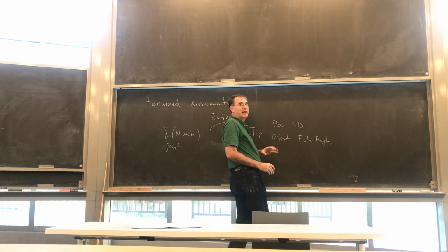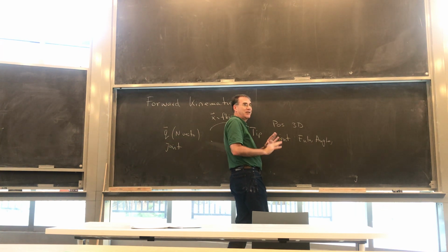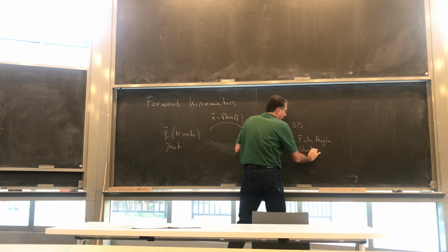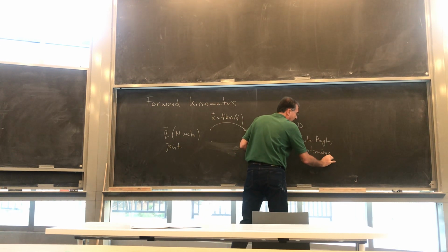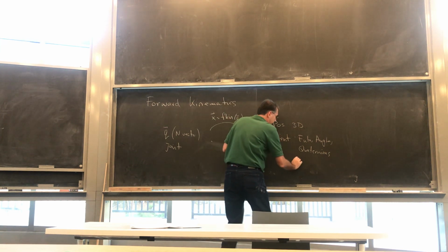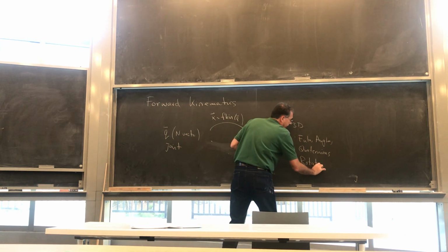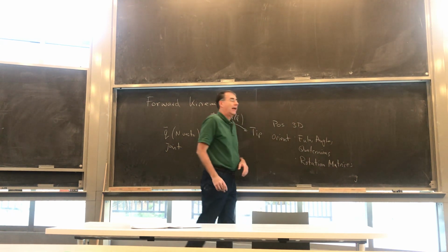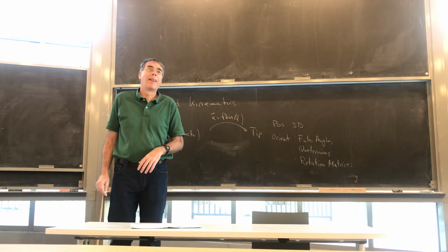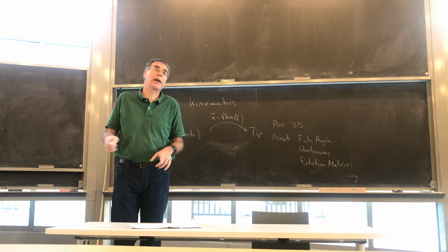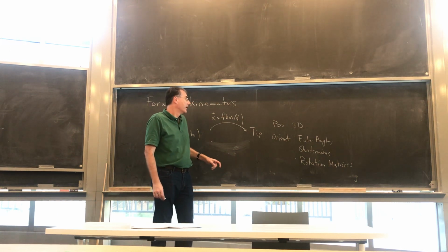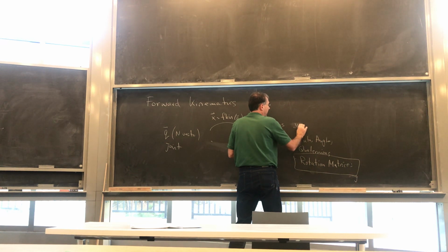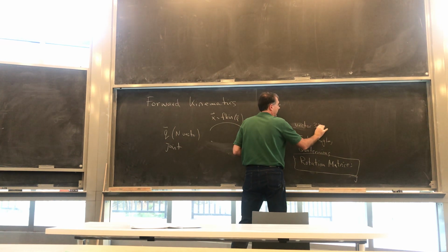If it's not clear, I don't particularly care for Euler angles. They just cause mathematical issues. They're kind of nice, but they cause issues. We can do quaternions. I actually really like quaternions. But it turns out, for this kind of math, rotation matrices are actually the one to do. They are easier to understand, and they're actually faster to calculate because concatenating them is easier than concatenating quaternions. So we're basically going to do rotation matrices, and this is obviously just the vector 3D for position.